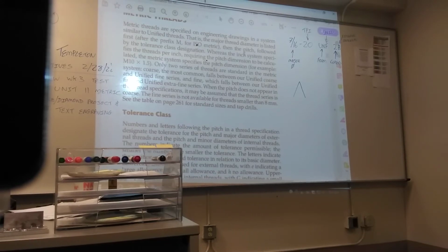What were you supposed to use? A thread gauge, thread wires. How much tolerance did you have? Use your OD mic to measure. So how could you manufacture those threads if you didn't know what tolerances you had? What you're supposed to do